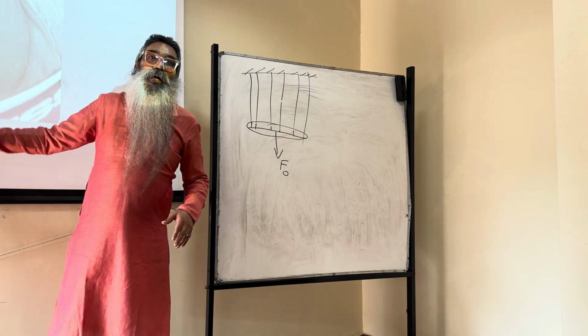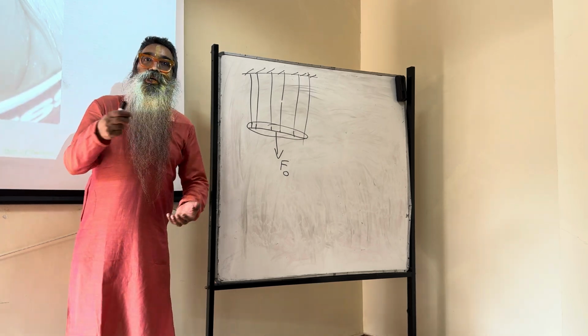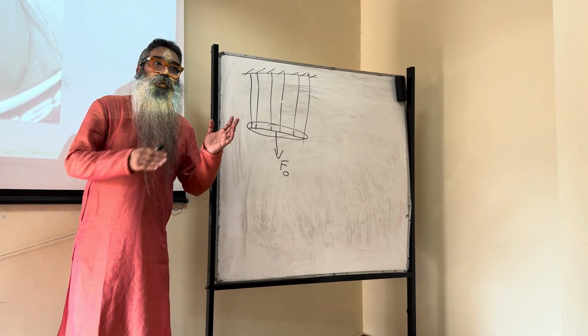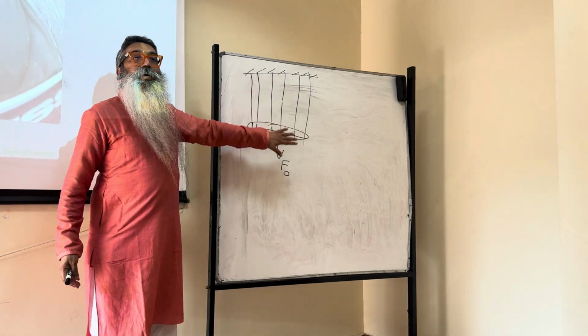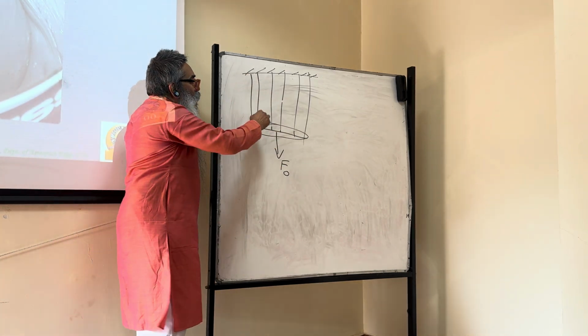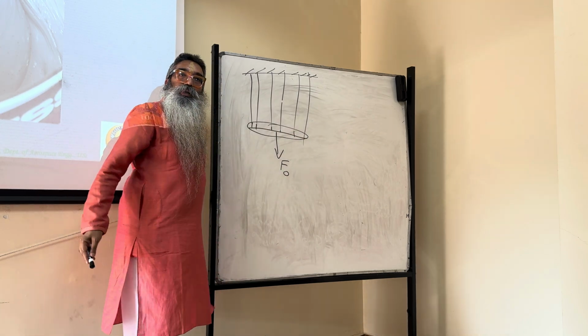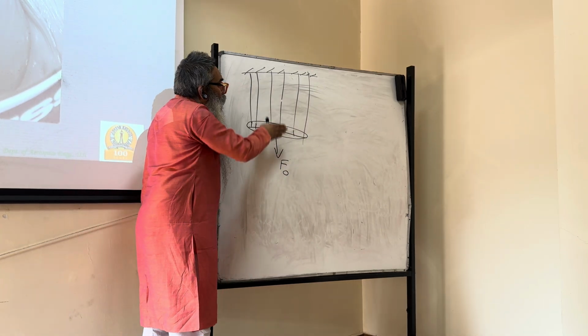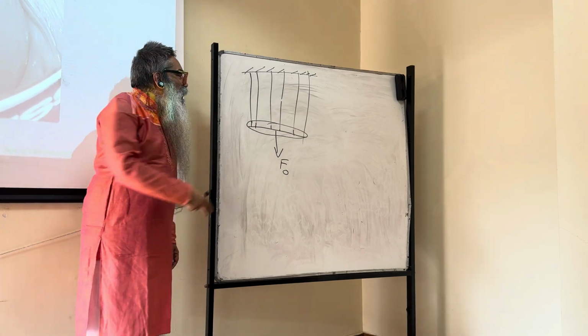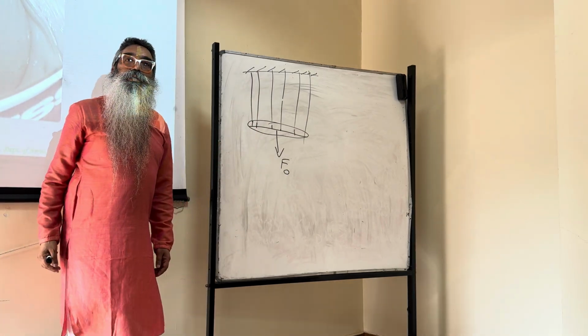putting it in the wet matrix, then doing an appropriate curing process, let's say in an autoclave, going through a set of pressure and temperature cycles so that it's a well cured composite. Once again, same bunch of 6 fibers in one case. In the other case, with a cut, after that I have done this process of putting it in the matrix and essentially getting this done, right?